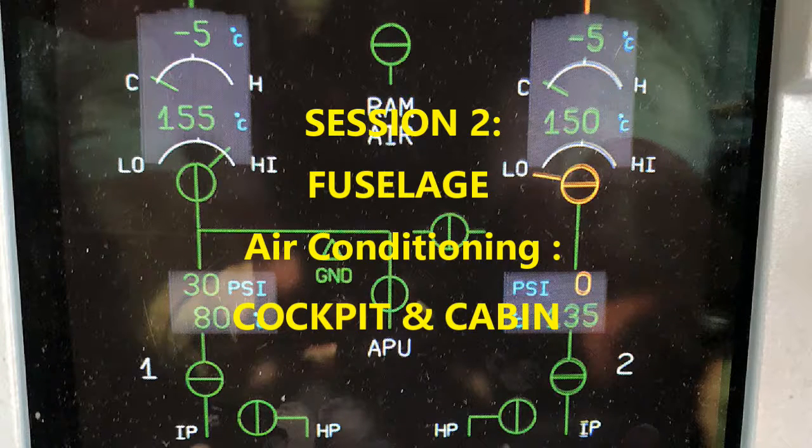And so it's going to be supplying it through the supply ducts that come from the mixer unit, enabling all that air to be there for everybody. So from the mixing unit, the air goes to the cabin zones through the ducts. There's different diameters of the ducts, and the ducts are installed in different places.